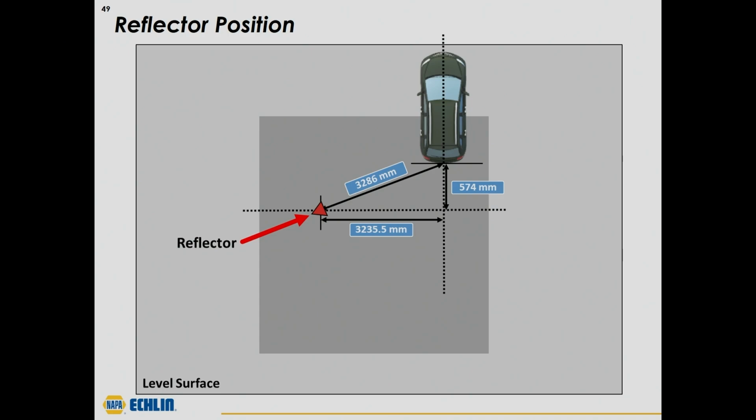However, they have a PDF where you can enter all of these numbers, and you can just measure straight back off your center line and then measure directly over to the side, which is a much easier way to measure it out. If you're using one of the aftermarket tools, something like an Autel or a Bosch unit, they're going to actually give you the right angle measurement right over there, so it's a little bit easier.